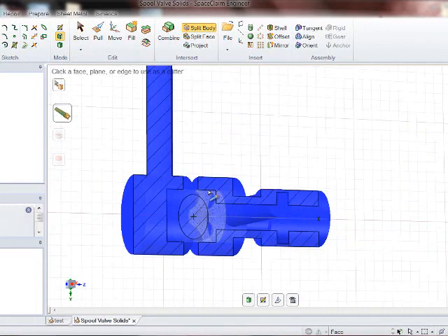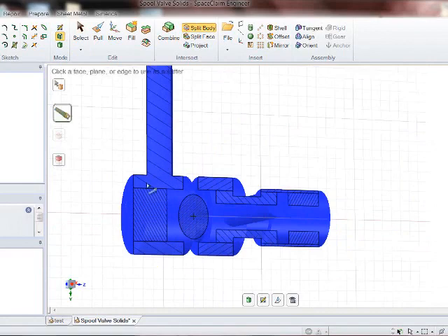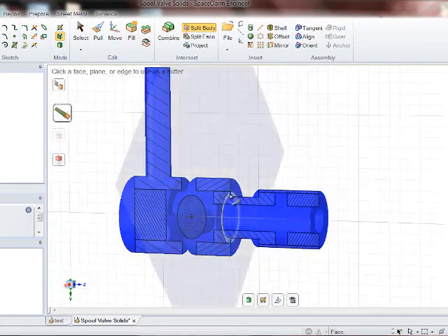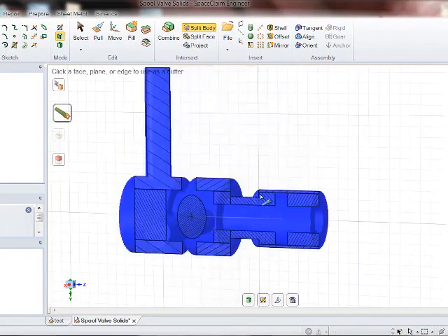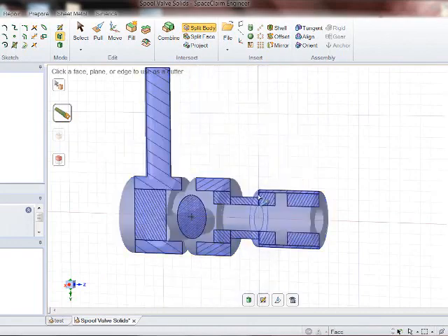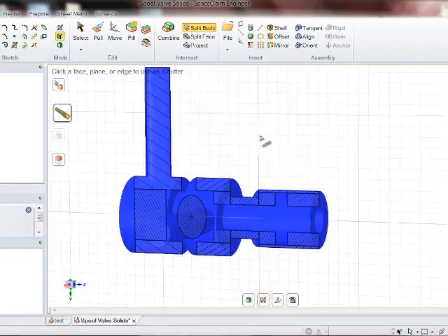This is the spindle outer diameter, and we can see it cut along here and here. So now we have this volume here for compression and expansion, and also here and here. We'll need to split it here and here as well to isolate these areas. We'll select the little annular region, and on the other side as well. And now we have all the cuts that we need.